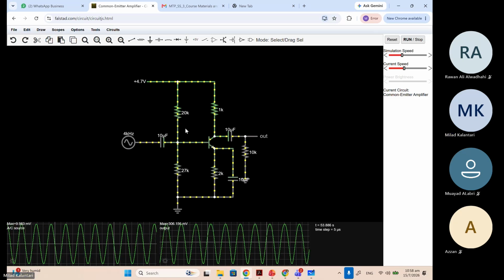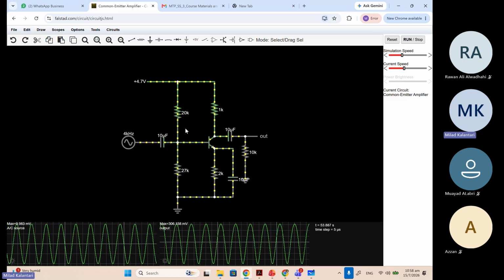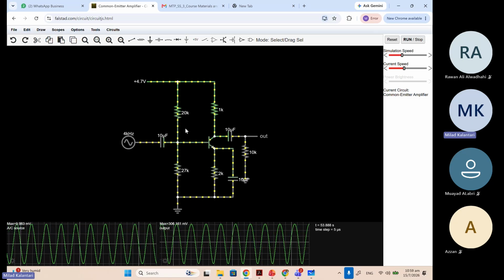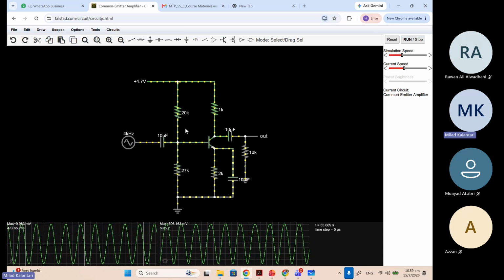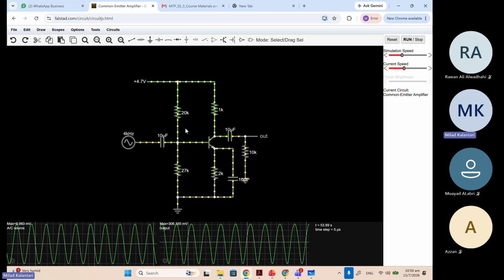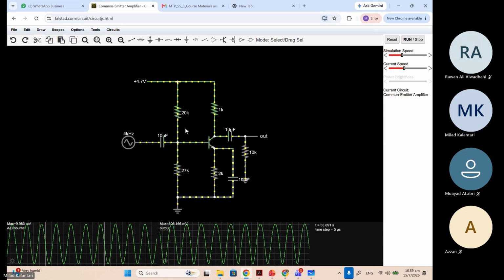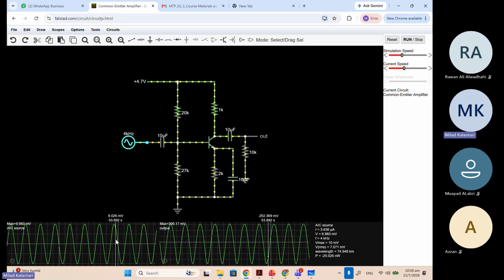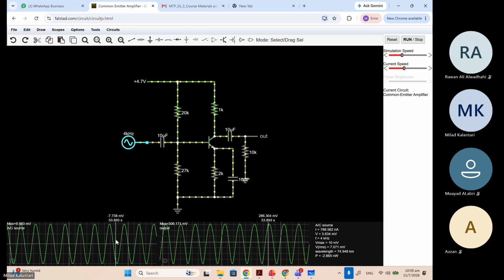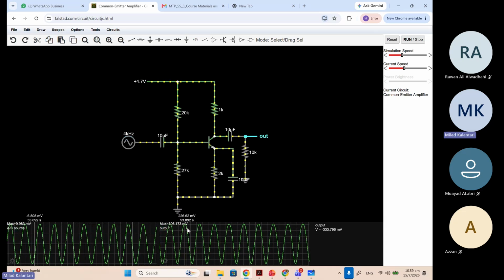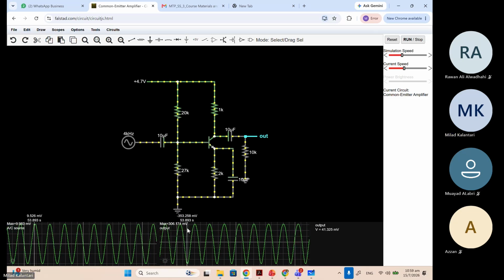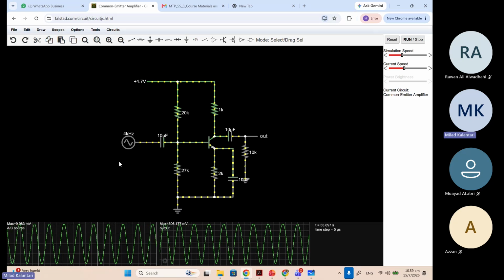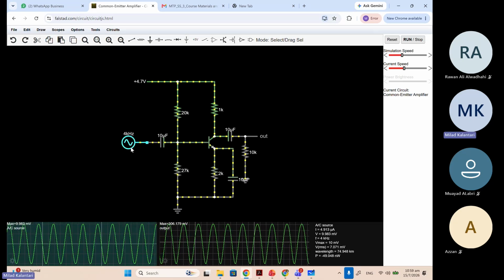Right. So the small signal model is what we come up with the GM and everything. We are just assuming very small, so we just take a derivation, right? The derivation is we are just assuming the GM is for very tiny variation around the DC. But if the variation is larger than what you assume, then the operating point of the device basically is changing, right? And then it means that the GM keeps changing over the cycle, for example, right?